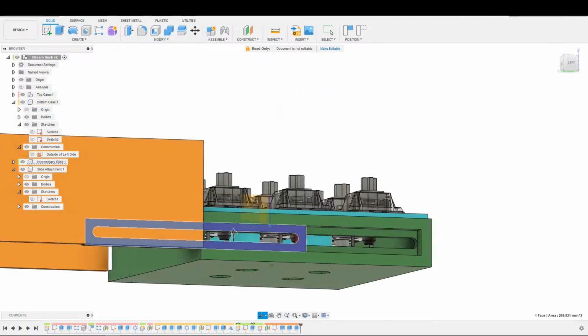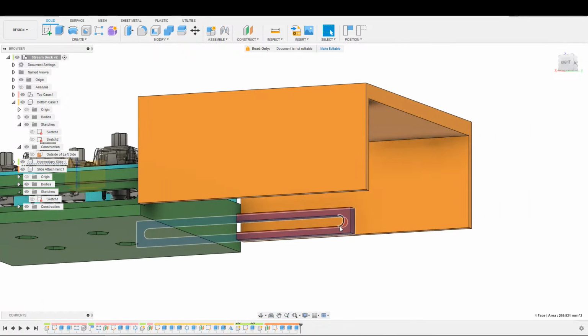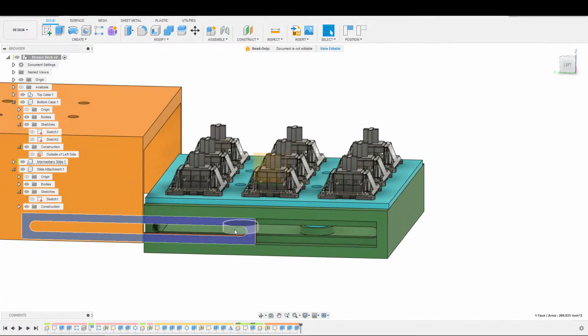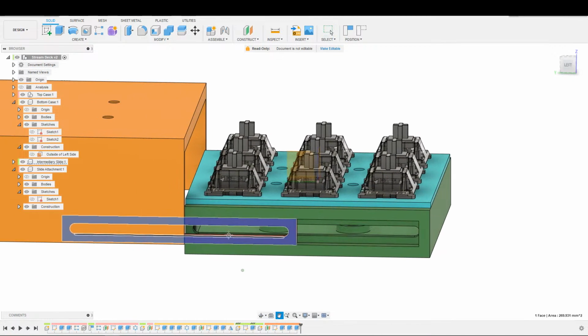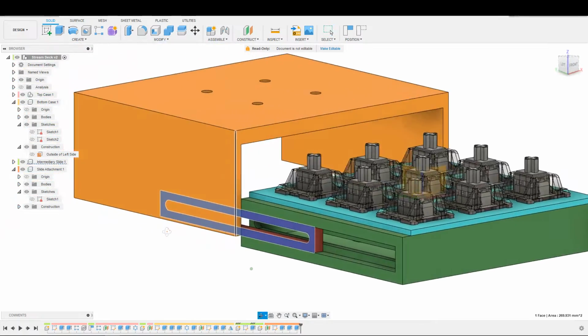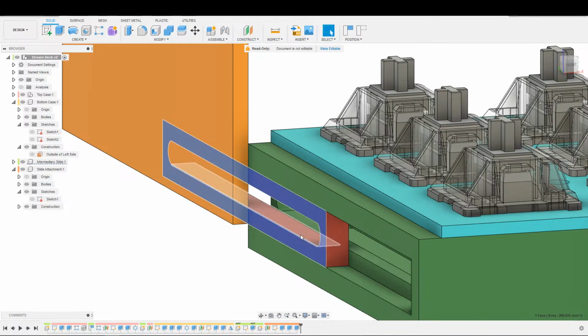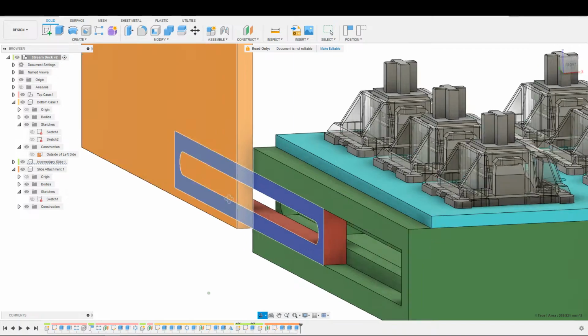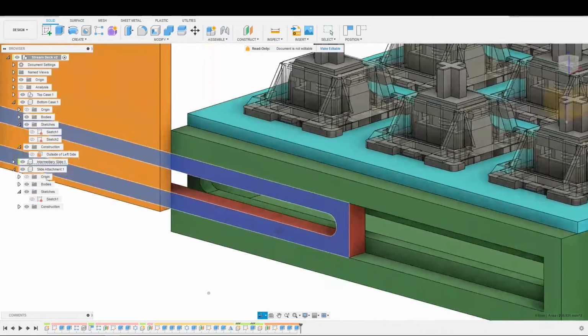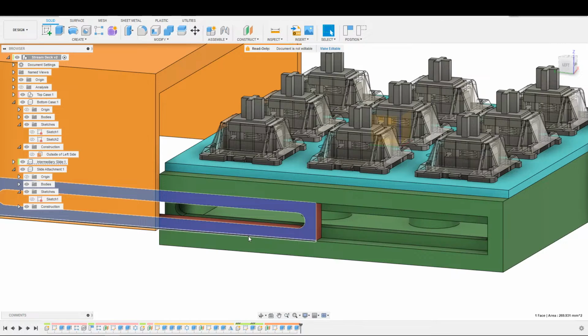So the next thing is the placement of the bolt here. Now, the placement of the bolt here should be against this back wall, and that is it, because we're going to have another bolt right here. So if we have another bolt right here, we're going to have a bolt head sticking out on this side, right? In that case, the bolt head sticking out on this side is going to need a slot to travel through on the inside wall here. So we need to accommodate that too, which means that we need more than this 2mm wall thickness because the bolt head is about 2mm of clearance. So we need to go actually up to like 4.